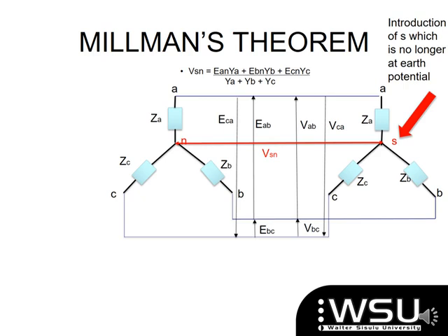So the common mistake made is that people utilized their line voltage angles in this equation, although they knew that you must divide those line voltages by the root of 3, but their angles, they didn't change them. And then obviously the other ones made the mistake that I've already explained on the naming convention.